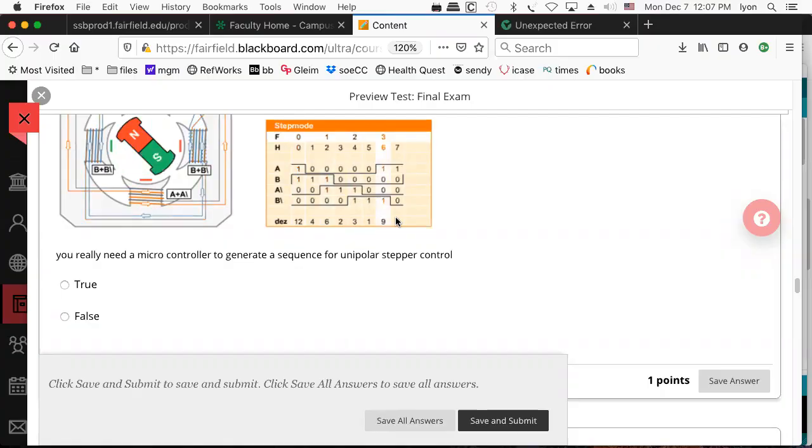And the answer is, it's a counter. It's a counter because it never visits the same state twice. So this is essentially a simple counter. It's just not counting ascending. And it doesn't visit every state, right? Because there's no state 0 here. It would normally be something that includes 0. There's no 10 or 11, 13, 14, 15, 16. Oh, I guess you would stop at 15. So yeah, if you look at it that way, this is a counter.